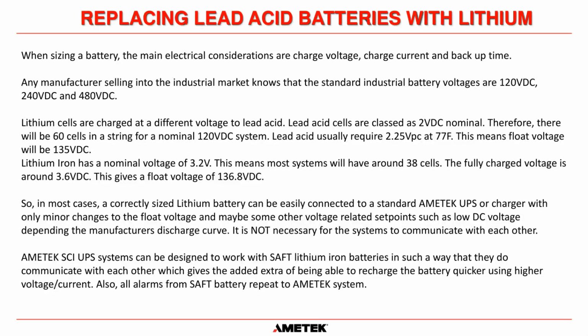And if you know anything about charging batteries, a lead acid battery usually requires 2.25 volts per cell float voltage to maintain a good state of charge. So that means the float voltage will be 135 volts DC. Okay? I hope you're following me here.